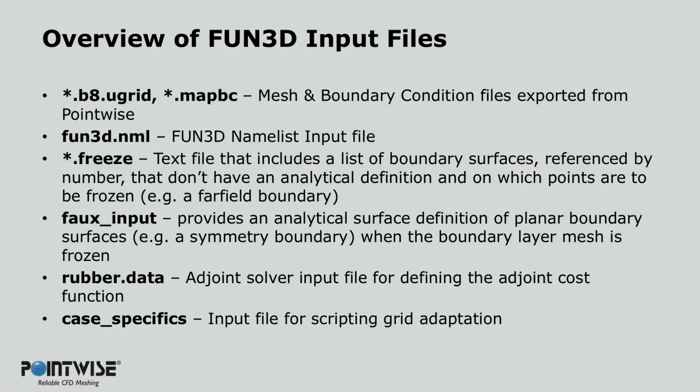Both the grid and the boundary condition files have been exported from Pointwise. A solver input namelist file is also required to define parameters that govern initial flow conditions, solver settings, frequency of solver output, as well as mesh adaptation specific parameters, which I'll cover in a bit more detail shortly.